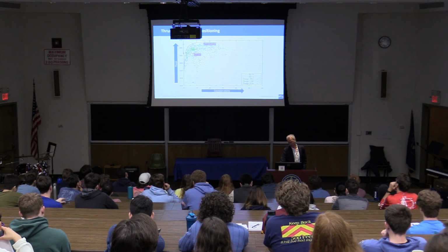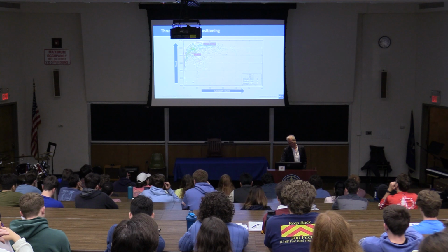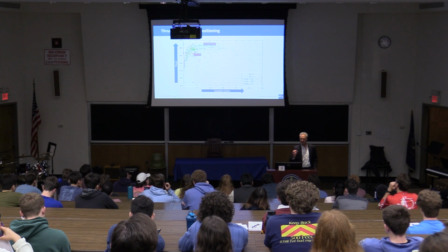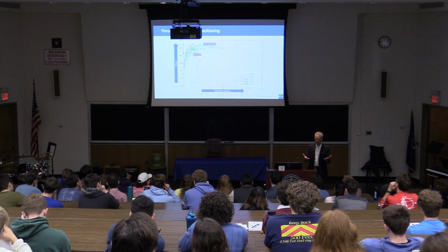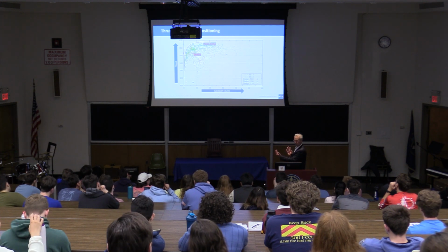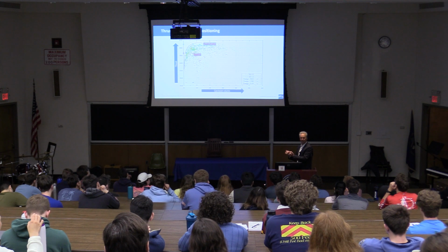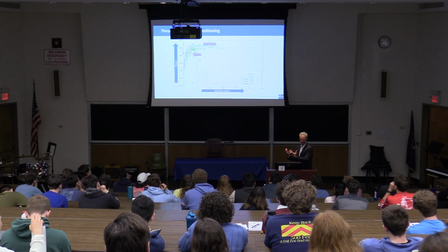You can now decide, okay, I have another design over here that's actually performing extremely nicely with regard to thrust. Same thrust, but cavitation volume has shrunk. Great. So we have less cavitation for the same thing that we produce, thrust.